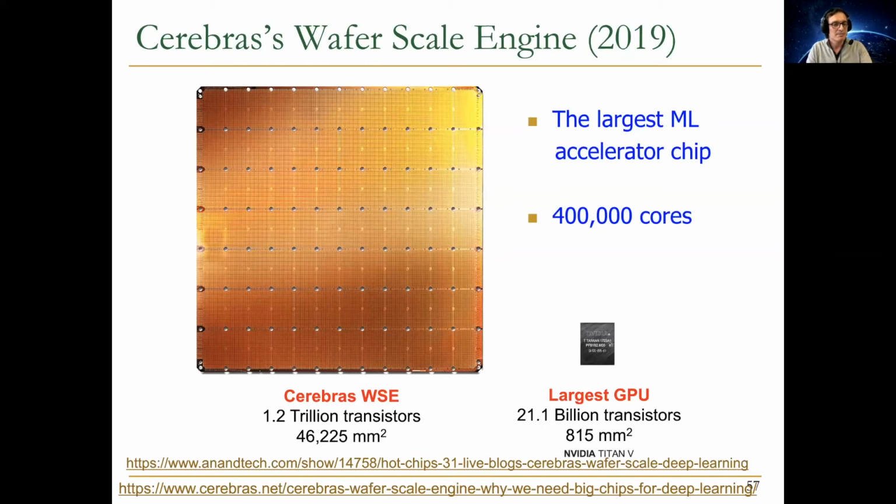But essentially, this system needs to have very high power requirements, for example. How do you cool this huge wafer that you can hold in your hand, right? How do you actually power up that huge wafer? How do you ensure that it operates reliably? Whenever you have a fault in any part of this chip, how do you ensure that that fault doesn't affect the whole system? Because the probability of a fault in a given chip now increases because the chip is the entire wafer, right? So there are a lot of issues that span the system stack, but this is happening today. It was not easy to imagine that this would happen 10 years ago. Well, I think if you're a computer architect and looking forward, yes, you could imagine it. But for the regular folk, let's say, it's not easy to imagine.